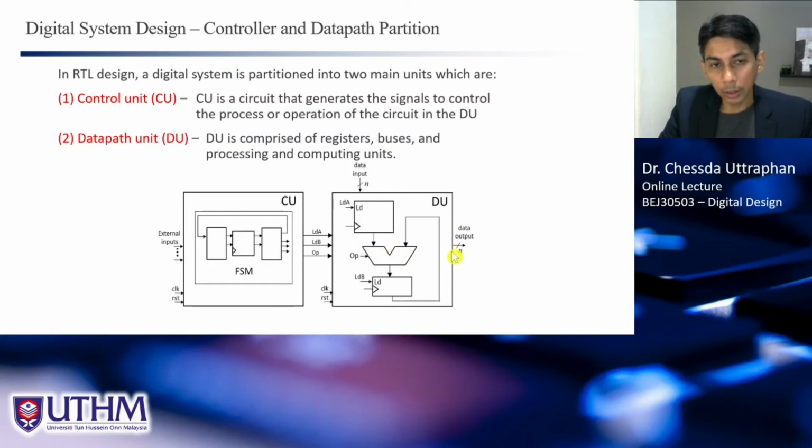But in order to make this work, we need to sequence the operation of the data here in order to get the output. So the data must come to this register at the right time and must go to this processing unit at the right time, and also at what time we want to load the data into this register, and at what time we want to send the data to the output.